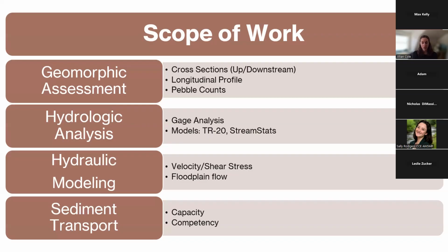Next, we would do a hydrologic analysis, which is needed for any structure design, regardless of the geomorphology, to ensure the proper sizing of that structure. However, from a geomorphic perspective, the hydrologic assessment will also estimate the bank flow discharge and base flow. So looking at some of those lower flows in addition to the higher peak flows as well. And that's really to evaluate typical flow conditions, which informs channel sizing and sediment transport.